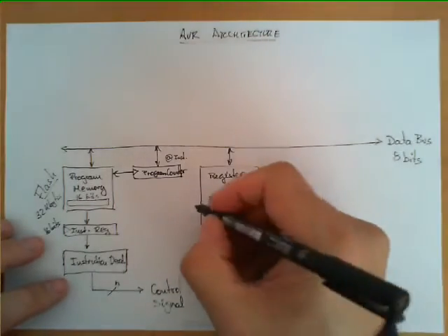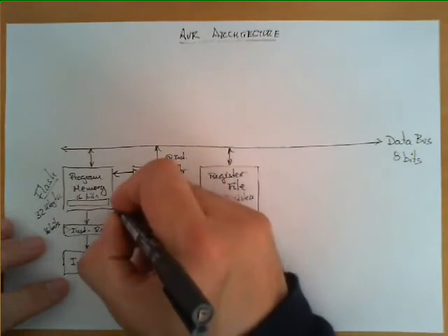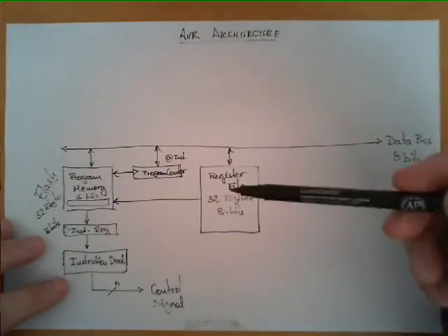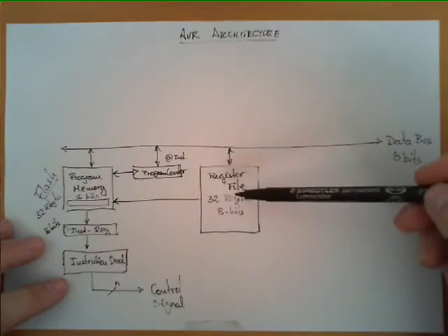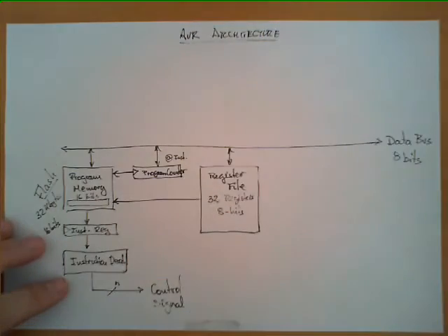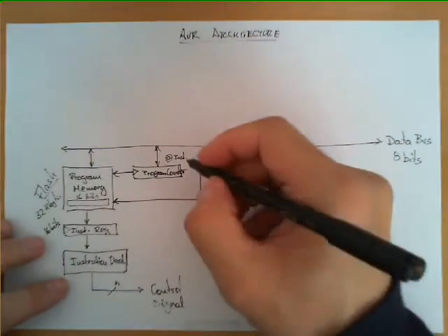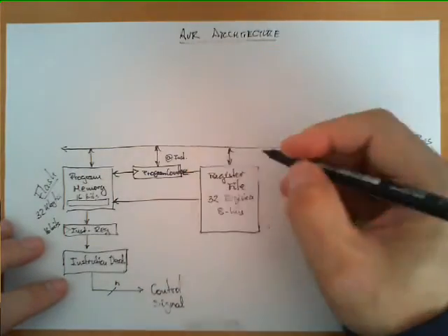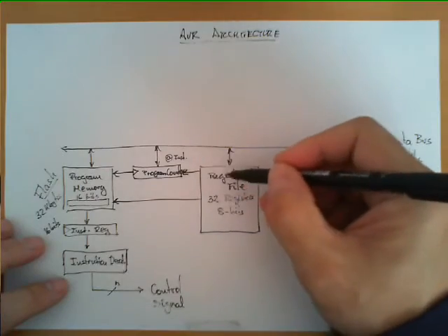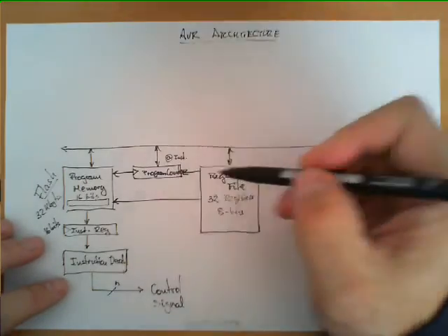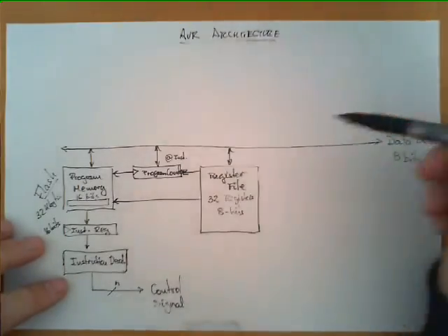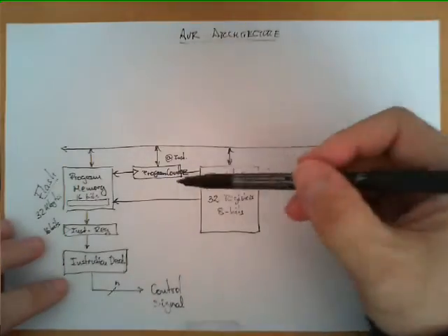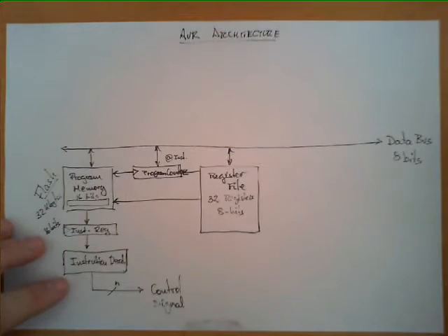One special connection is between the register file and the program memory. In some cases, what we want to do is to get some data from the register file and use it also as an address to access the program memory. Another important functionality of the register file is to load a certain value in the register file into the program counter. And this is typically done in instructions that change the value of the program counter, namely the jumps.